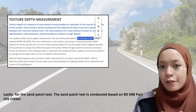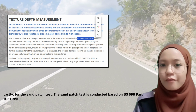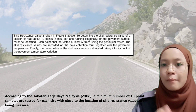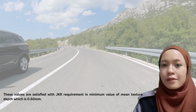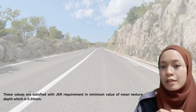Lastly, the sand patch test is conducted based on BS 598-105:1990 according to the Jabatan Kerja Raya Malaysia 2008. A minimum number of 10 point samples are tested for each site, close to the locations where skid resistance values are being measured. These values satisfy the JKR requirement of a minimum mean texture depth, MTD, of 0.5 mm.